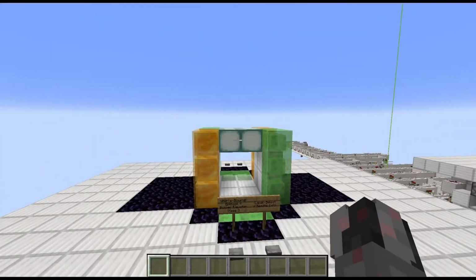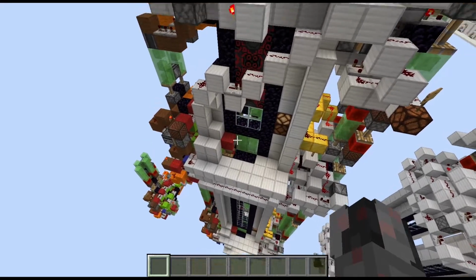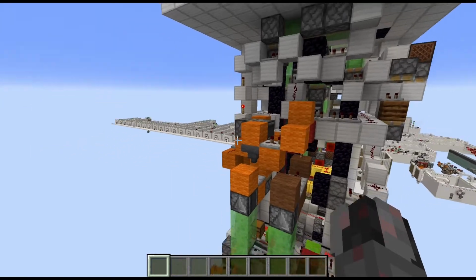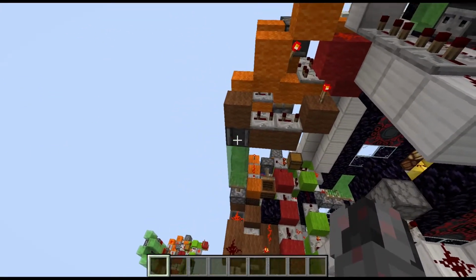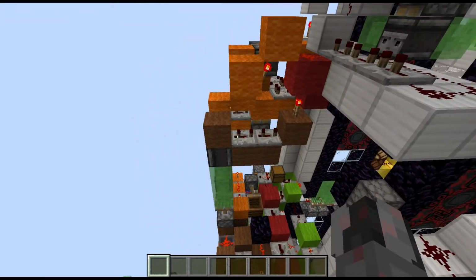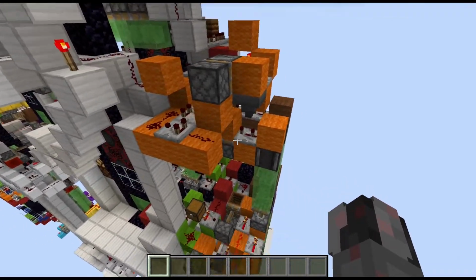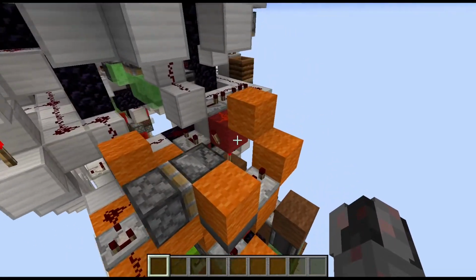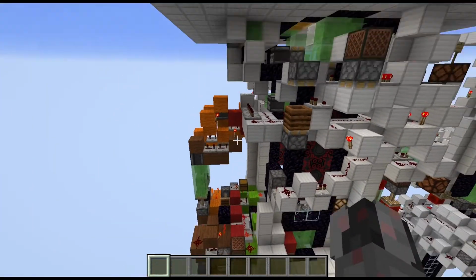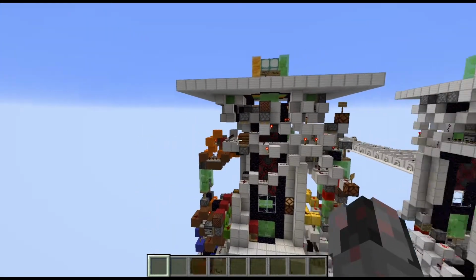So if you press the buttons, you are sent to the next floor below, where then you can make a direct level select. Nevertheless, I have at least the receiving component in there, so the mostly constantly delayed part for the stop pulse and the programmable delay for the start pulse. Again, this runs into an AND gate and triggers the circuitry. So as you can see, the topmost floor is much simpler than the other floors due to the limited functionality there.